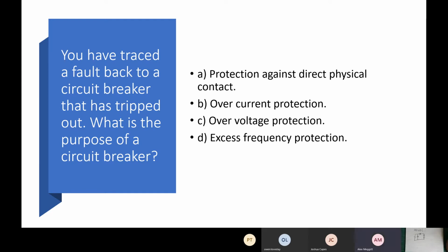All right with that one? So the RCD is for leakage, isn't it? Yes. The MCB, the circuit breaker, is there to protect against overcurrent. We use an RCD to protect against fault current going somewhere it shouldn't.